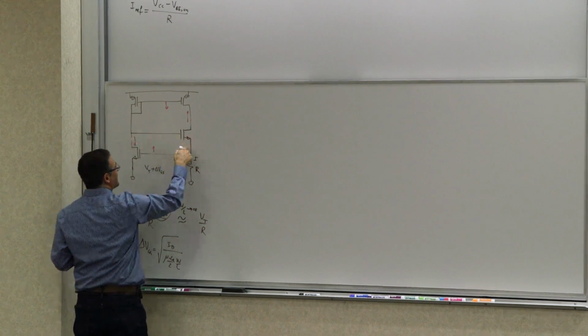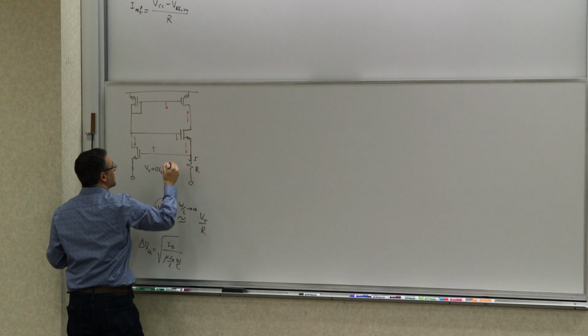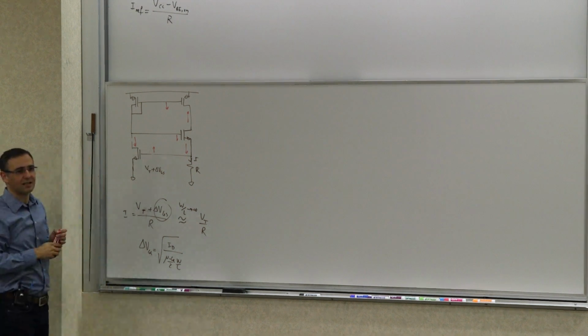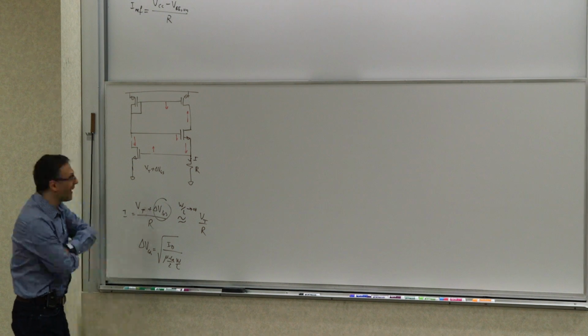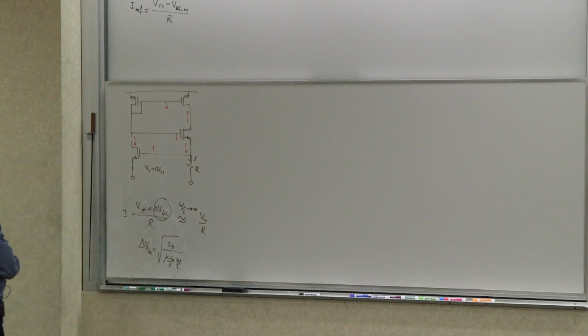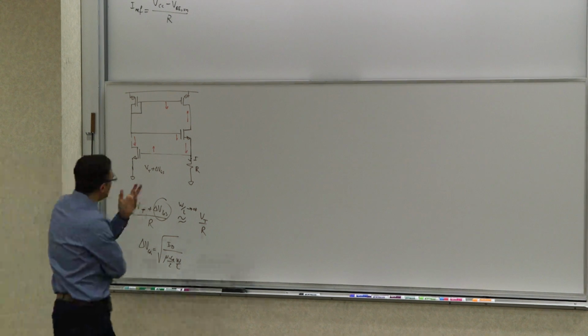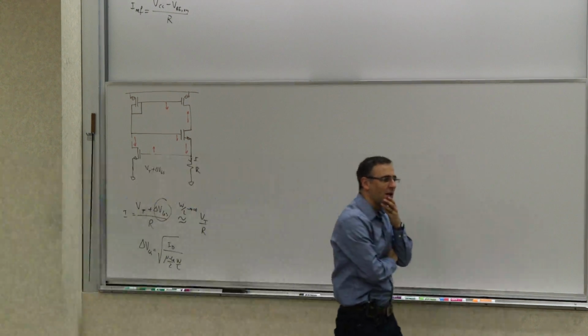But you can see that now this is a follower. So this goes down, this pushes down. So now the feedback sign is negative, because if this goes up, it's being pushed back down. But other than that, this is one way to generate a threshold voltage reference, right?